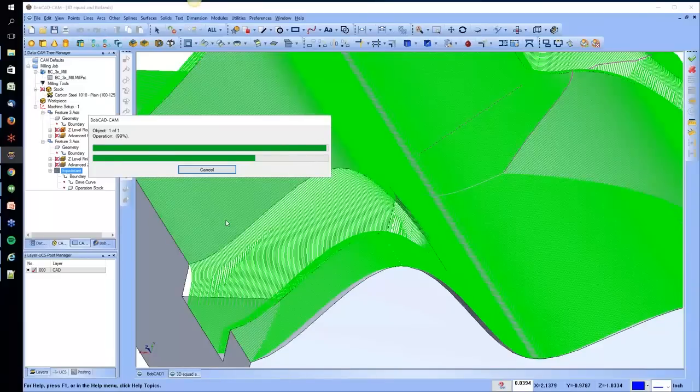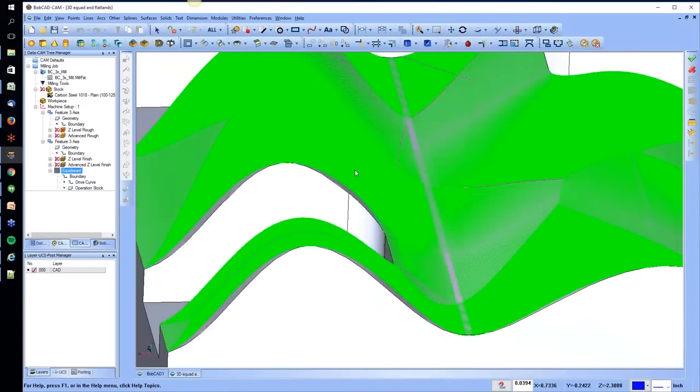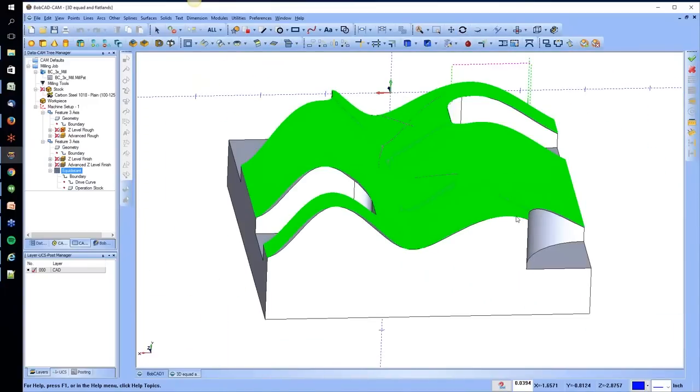So picking the proper toolpath is very critical because as you guys saw with a Z-level rough and the advanced Z-level finish, you've got a lot of rapid moves that aren't needed, a lot of traversing back and forth that isn't needed. Well, with equidistant, what it's going to do for you guys, and this again comes down to picking that proper toolpath, is it's going to start and it's just going to start moving around the model. Not lifting up. It's just going to keep moving over.